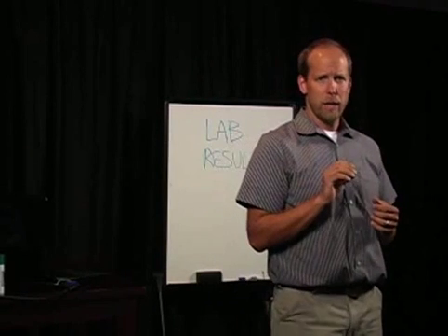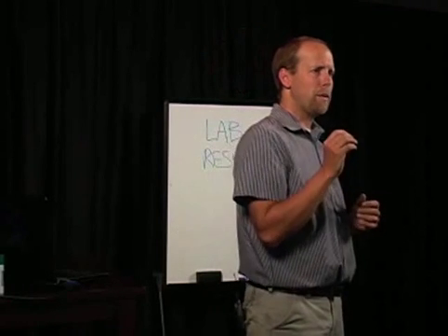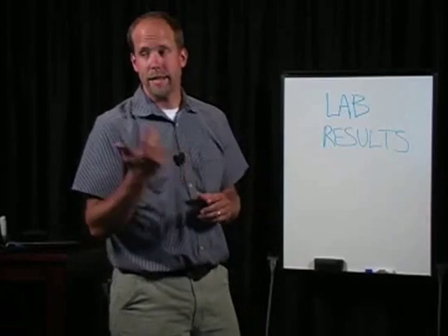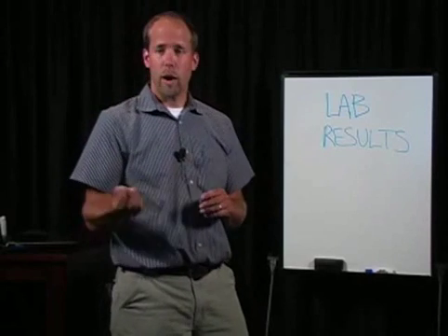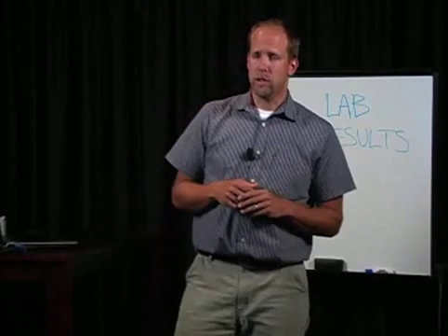Another thing that should be in the mold report is property information. This should include the property address, the size and age of the building, number of occupants, and the date of the inspection and time of the inspection. The weather conditions should be included as well.